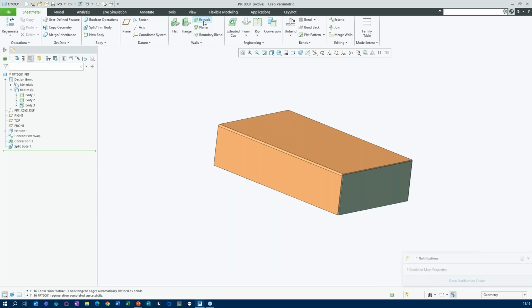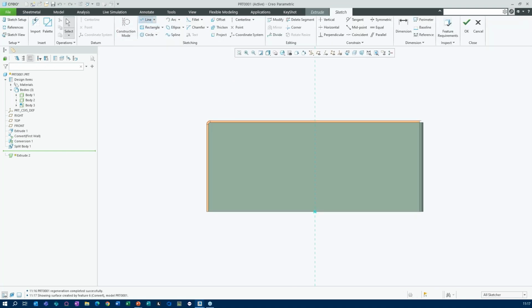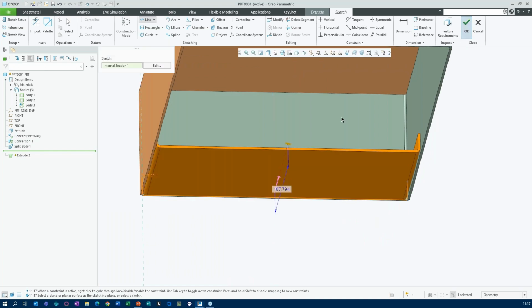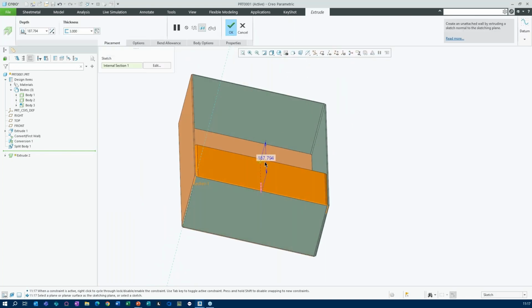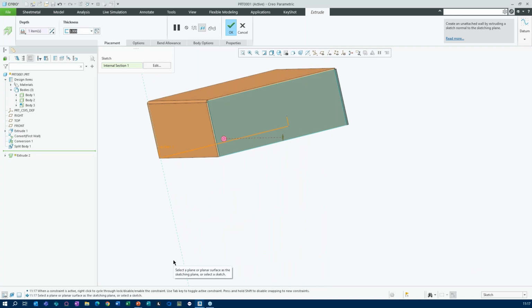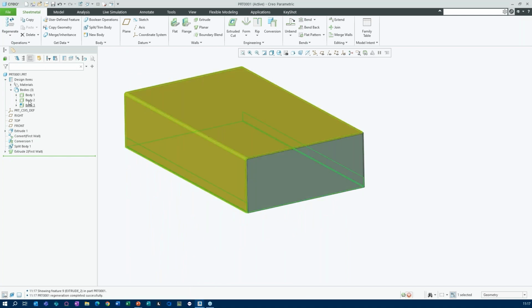And in this case, I can create a new body based on other thicknesses and other values. Looking where that equal is. So I'm making kind of a U shape at the bottom, which gives me, of course, automatically a bend because I'm using extrude. I'm snapping this to the end with shift, and I will set here that my thickness will not be 3 millimeters, but 1 millimeter. And I want that to be a thin plate. So 3 bodies,